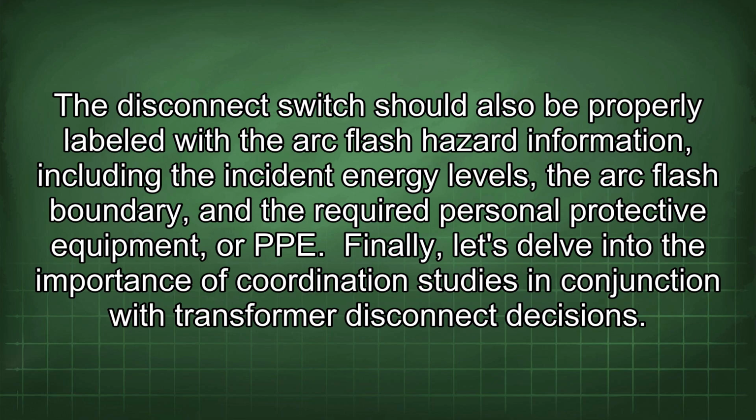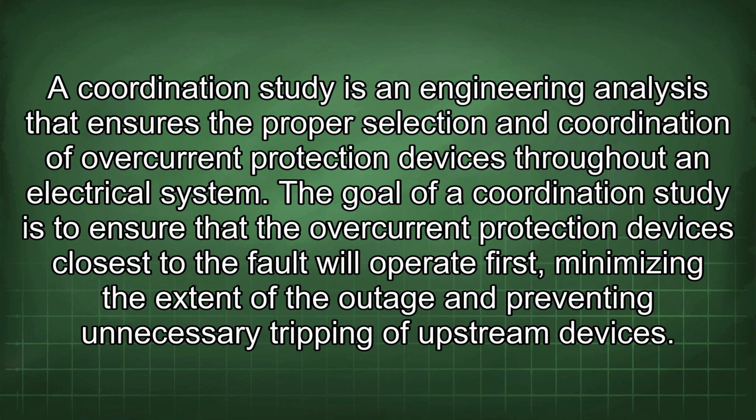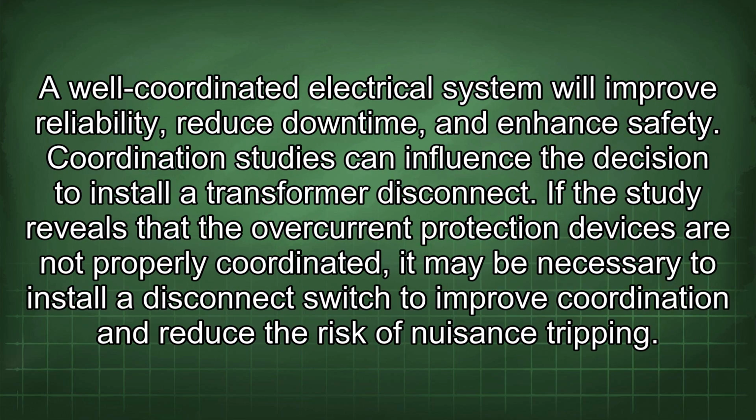Finally, let's delve into the importance of coordination studies in conjunction with transformer disconnect decisions. A coordination study is an engineering analysis that ensures the proper selection and coordination of overcurrent protection devices throughout an electrical system. The goal of a coordination study is to ensure that the overcurrent protection devices closest to the fault will operate first, minimizing the extent of the outage and preventing unnecessary tripping of upstream devices. A well-coordinated electrical system will improve reliability, reduce downtime, and enhance safety.